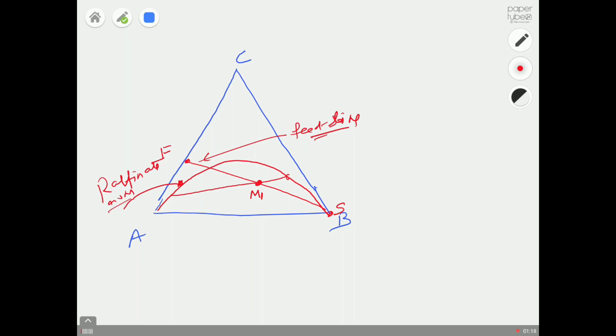You must watch my previous lectures. So this is 100% carrier liquid. The arm which is near the carrier liquid, we call the raffinate arm. If you don't remember which is your raffinate arm and which is your extract arm, just look where your solvent is. Wherever your solvent is, that side will be your extract arm. So this will be your extract side.